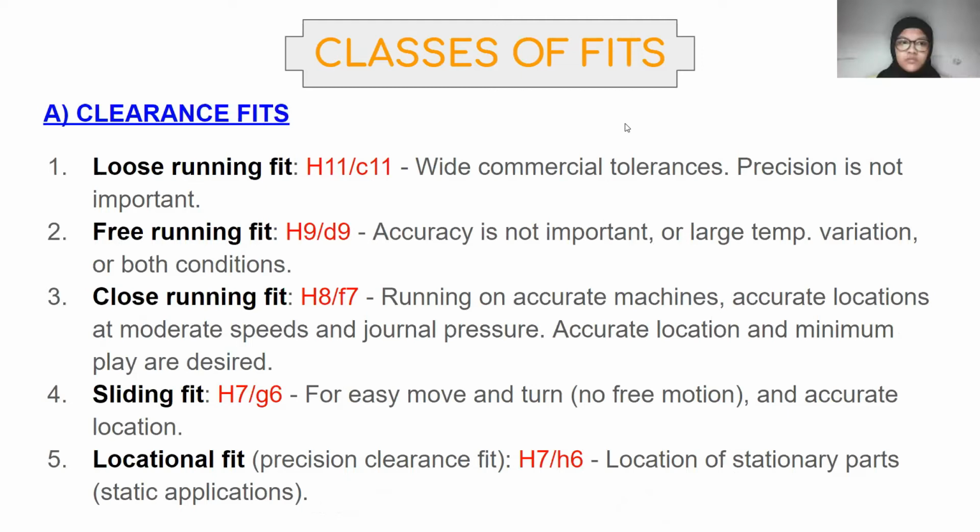Thank you, Syamimi. I'll present the classes of fits. There are three classes. I'll explain the first class, which is clearance fits. For clearance fits, there are five types: loose running fit, free running fit, close running fit, sliding fit, and locational fit.